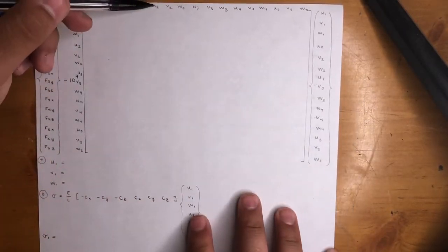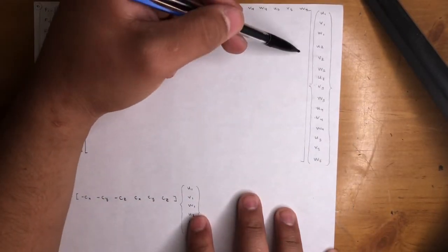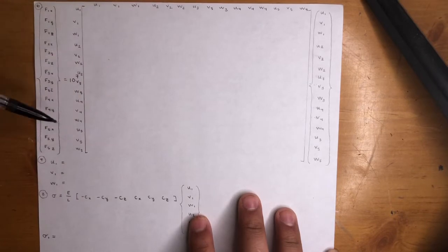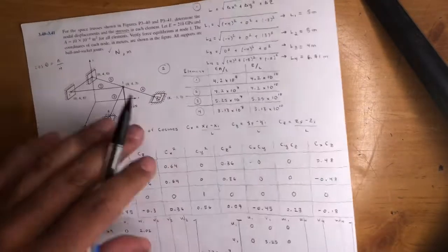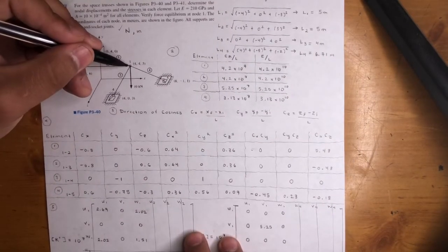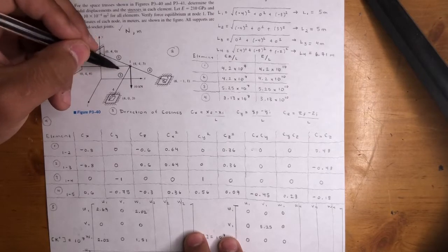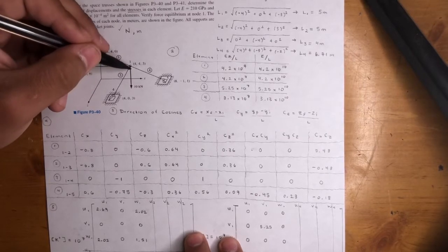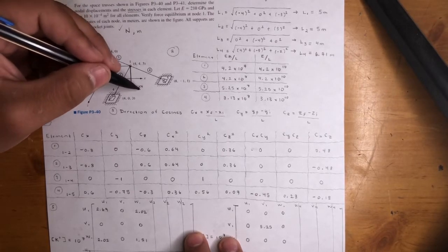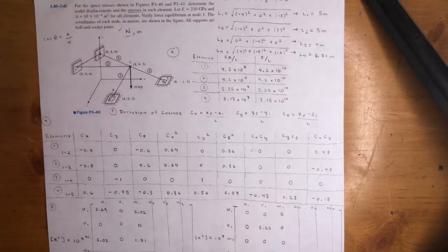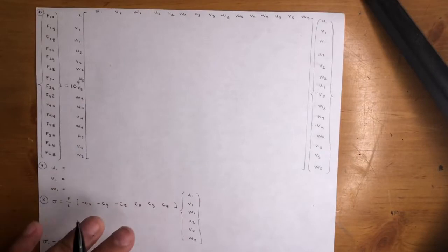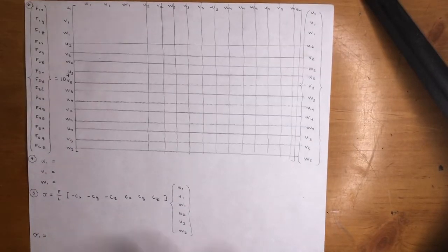Look, I'm gonna apply the U2 all the way to W5 boundary conditions, the same going down, and then I'm gonna go ahead and add the force numbers. Because we know at force 1x, there's no force being applied in the x direction. There's none in the z direction, just a negative 10,000. Again, we want newtons, remember, in the y direction. So that's what we're gonna do, and just give me a second. All right, so I went ahead and did that, right?